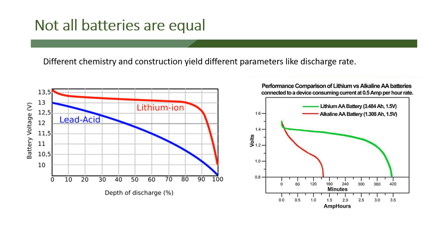More and more of the amateur radio community is moving from traditional lead acid batteries, which are the kind of batteries that are in your car, generally speaking, and moving to lithium ion batteries. And you can see from the left side that a lead acid battery at 13 volts begins to have a discharge curve that is fairly gentle going down to 100% discharge, but it means that you're not staying at 13 volts for very long. You're constantly under load going down over time.